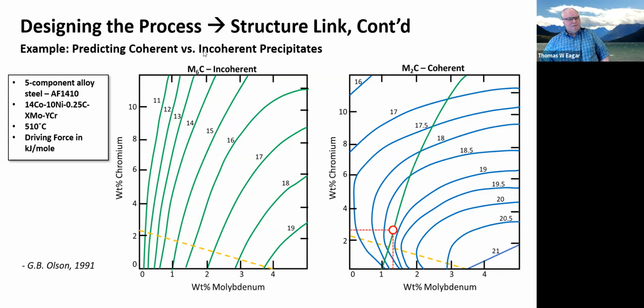One would think, yeah, if you want the best toughness in your weld zone. I'm not sure the bicycle people are worried about that. Now we're getting to the question of the plastic zone size in fracture mechanics. That's another topic. Am I right? Can you form austenite in a weld? Oh, yeah. In fact, we call it MA constituent, martensite austenite. It has its own acronym nowadays in welding.